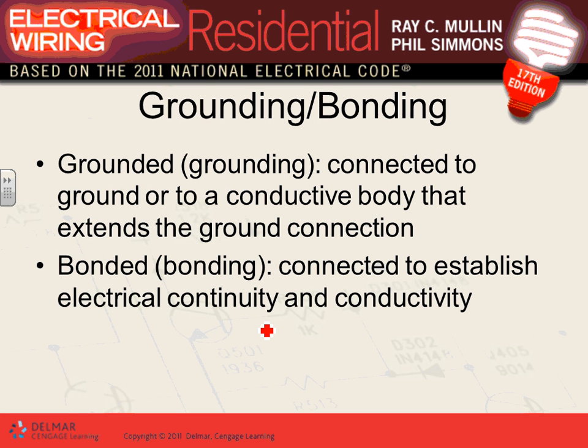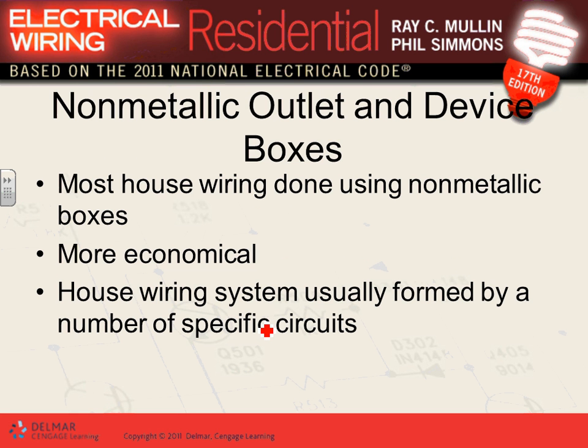So what do we do with this? We bond it. Then we bond that frame. The whole frame at one point will be bonded to the equipment grounding conductor. So if that happens, the circuit breaker will trip. That's called bonding. Bonding the things that have nothing to do with electricity, like that grid. Really, it's just there to mount electrical equipment and all these tiles. But it's not meant to be electrical equipment. So we bond them. A tank sitting there that could be energized and have a pump on it, we bond it. So we bond them to facilitate the operation of the overcurrent device, so it can save people.